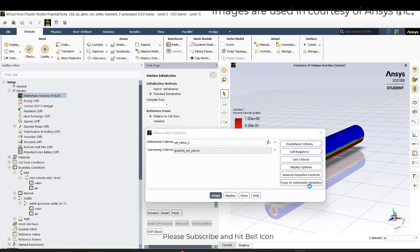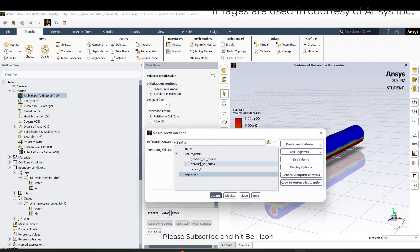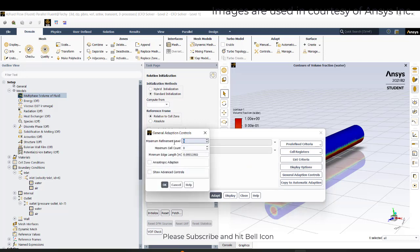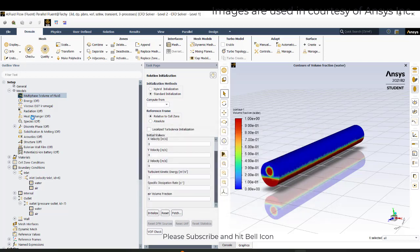In the general adaptation control, you need to select the refine option. The refinement level should be 2, and the maximum element count is 512,000 nodes, so it should not cross that. Just give it as 1, because if the count crosses that, then again it's a headache for us. The minimum cell orthogonal quality I'm keeping at 0.05, and adapt, close.